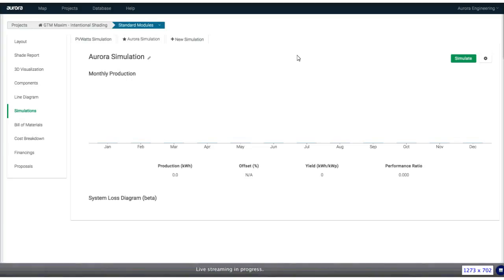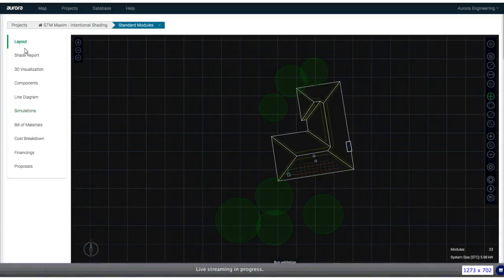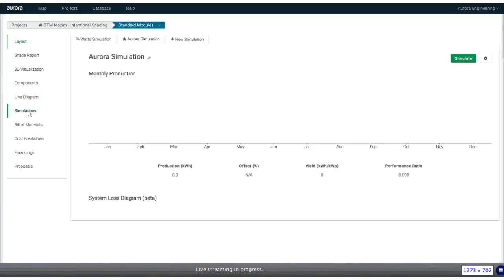And then we wire all these equivalent circuits together. So for example, with panels, we wire them in series and in parallel to exactly reflect the stringing configuration in a design. So in this way, we're very accurately able to estimate the performance of a design throughout the year.